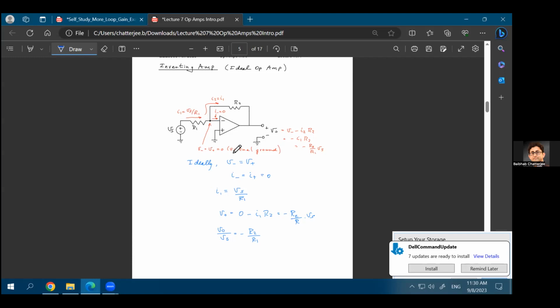When you have negative feedback, if T increases, it gets more like an ideal op-amp. Yes, because what does T increasing mean? That A is increasing, so it becomes more like an ideal op-amp. Good.